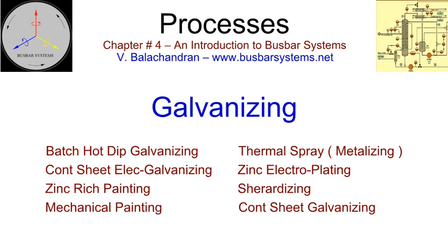Should there be an exposed area of steel, damage caused during transport, loading, unloading, or installation, zinc in the neighboring area will act as a sacrificial anode, protecting the steel cathode in the electrolyte. Such practices, called cathodic protection, are universally adopted in all industries to prevent corrosion.